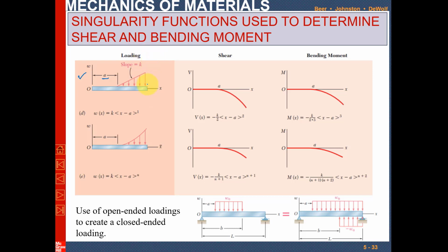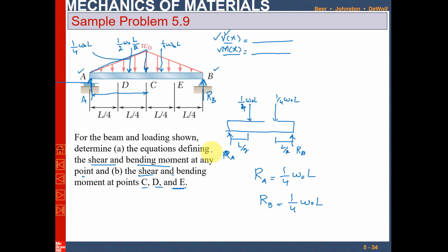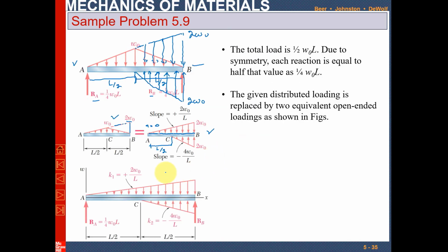Again, let me write this as well. For this loading we can see that the shear force equation is equal to minus K over 2 into x minus A to the power 2, and the bending moment will be equal to minus K over 6 into x minus A to the power 3.